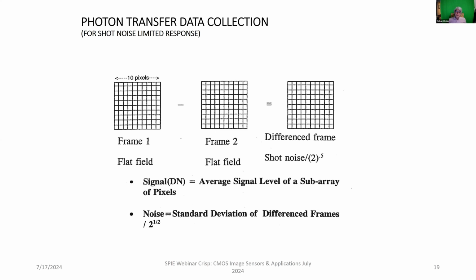But we'll take that difference frame and make some measurements on it. What we do is take a sequence of these exposures starting from no signal, where we can measure read noise, all the way up to saturated image sensors. We may take 50 pairs of exposures, or we might take 20 or whatever, but take a number of these as you vary the signal intensity.